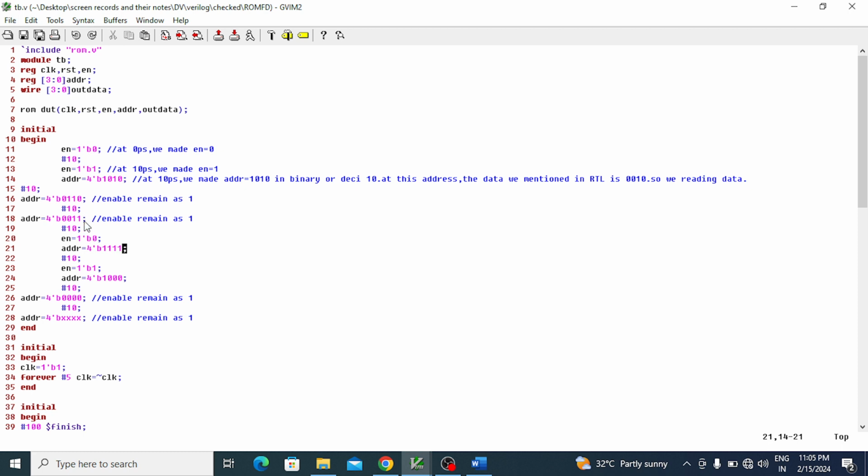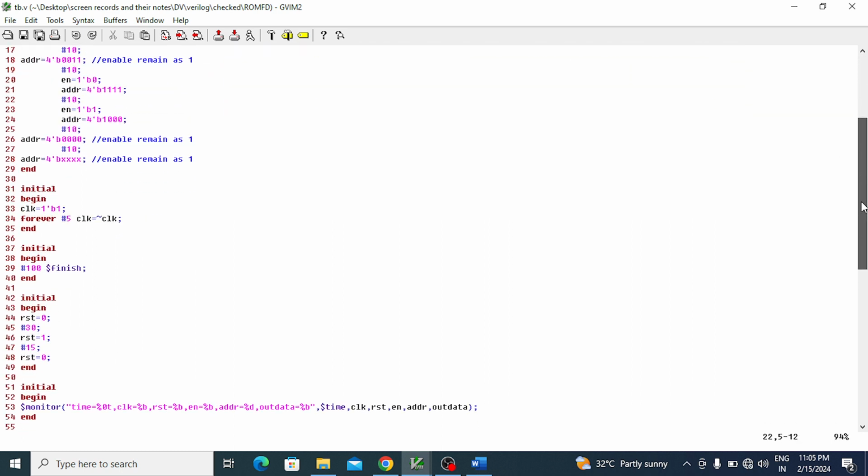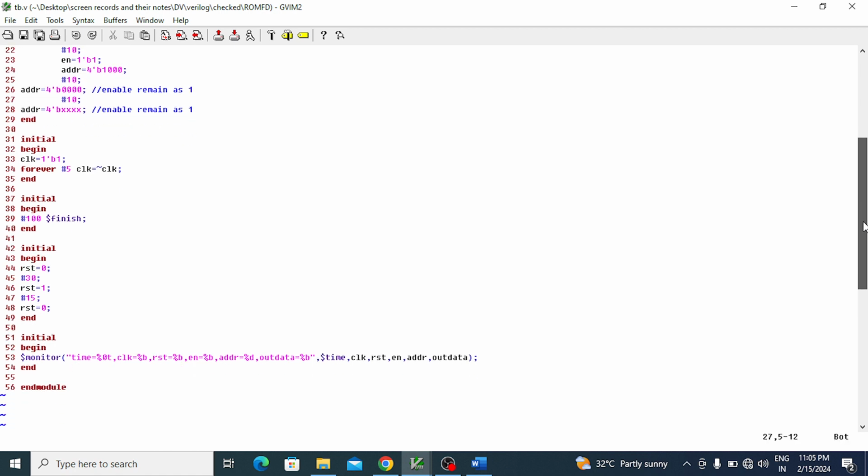I already generated some input data in the design code itself, and I have to generate some clock. So this initial block is for clock generation. I took my initial clock position as 1 and time period as 10, and as an example the finishing time is 100. Because I am using clock forever, that's why I used finish.